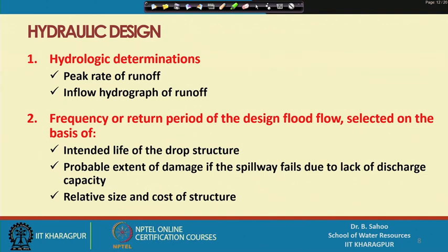For the hydraulic design, we generally consider two types of criteria. One is your hydrologic determinations, which is based on the peak of runoff in the gully or in the channel, then the inflow hydrograph of runoff. Second is the frequency or return period of the design flow selected on the basis of intended life of the